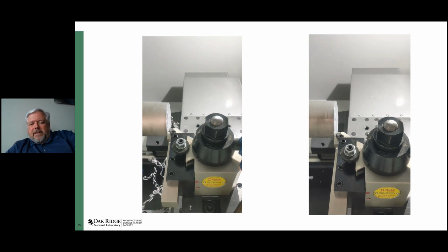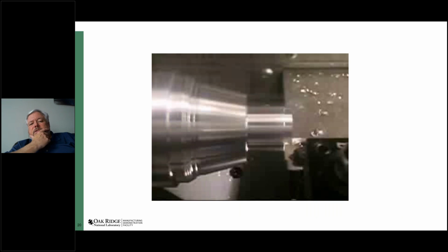All right, I have another video here. So this one's going to show a few different operations. I'm going to show the turning on the outside of a cylinder. I'm going to show the turning of a cone. I'm going to show a boring operation as well. So realistically, any of the single point material removal operations that you would do on a lathe, this strategy will work, right? I'm using the machine, so the machine axes are making this motion anyway, so they can move along those surfaces, but I'm superimposing this oscillation on top of that.